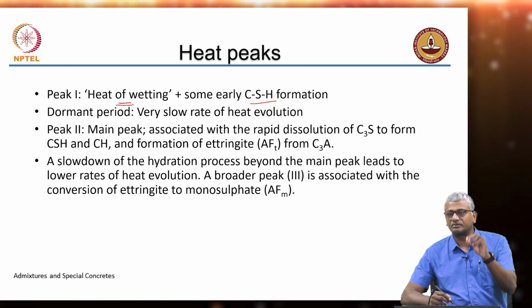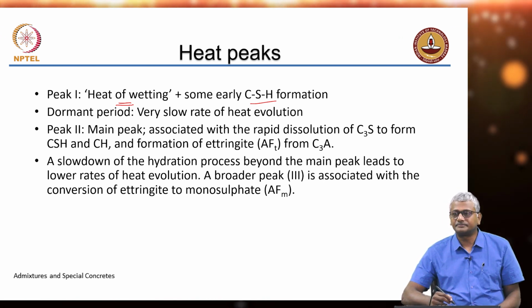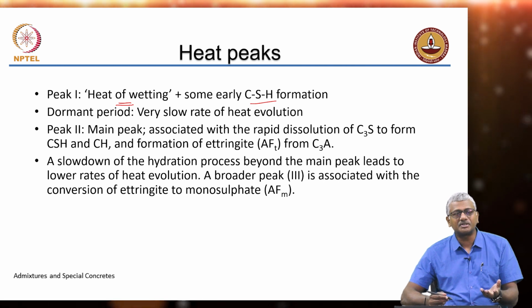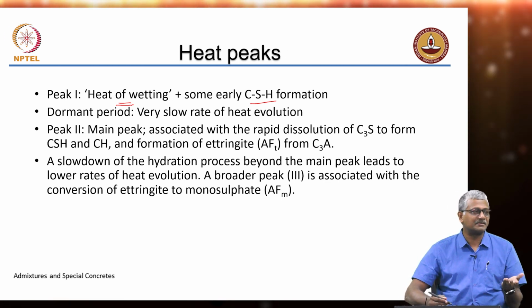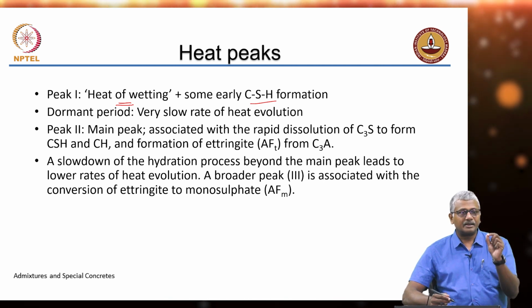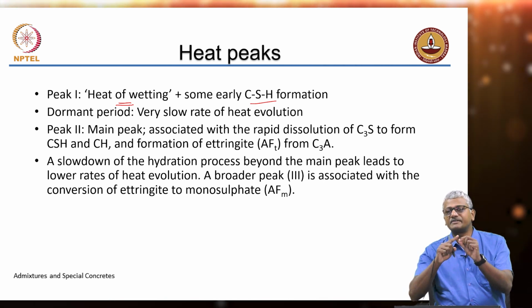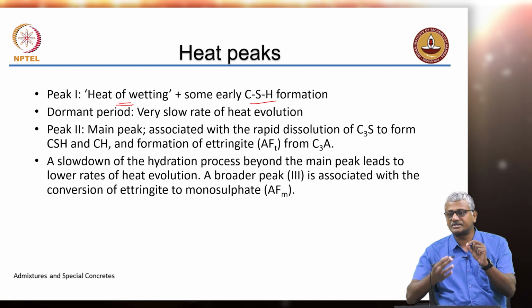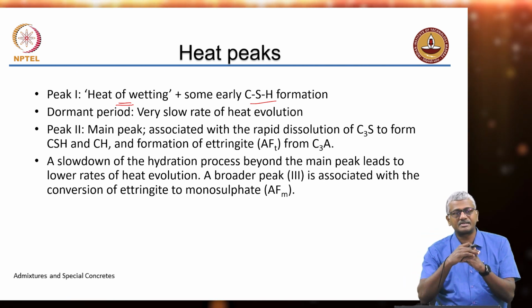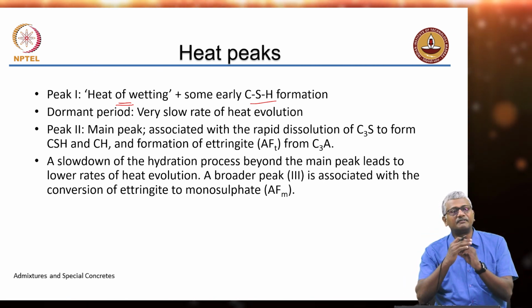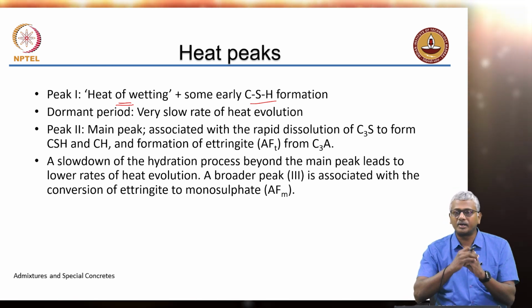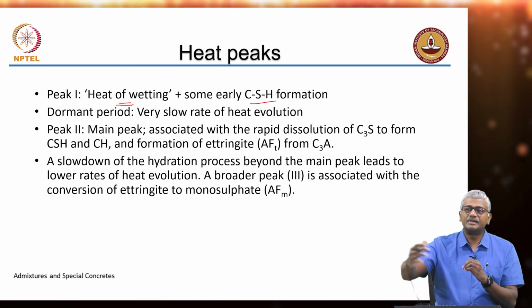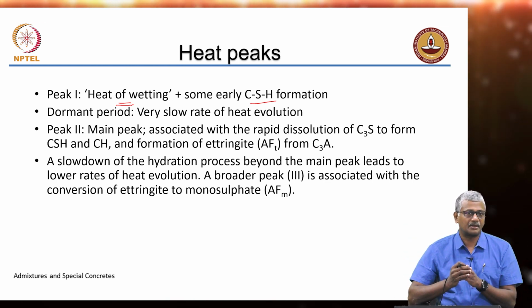Even when you mix water into atta, of course, we can't measure that heat evolution, you can't feel it in your hand also, but still there is heat evolution. Why? Because any particle will have surface atoms which are at a high energy level. When water touches the surface, the interface that is created between water and the surface atoms has now a lower energy level. So, excess energy is released as heat, okay.